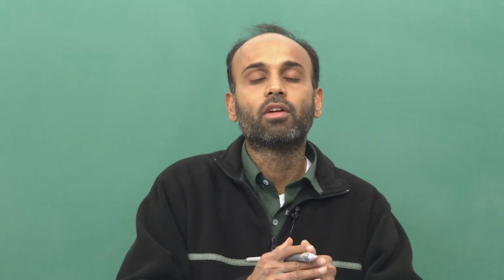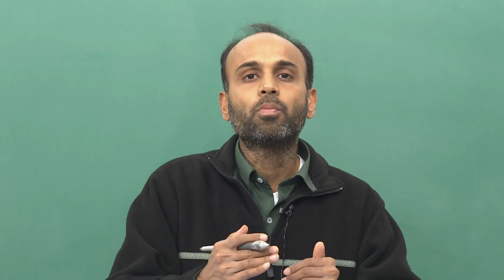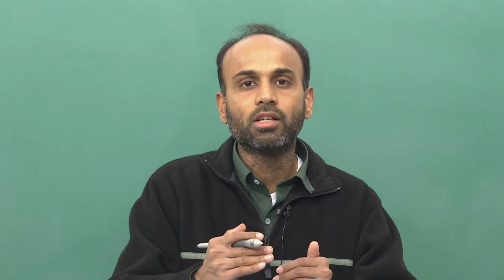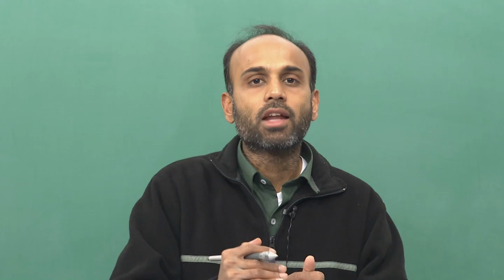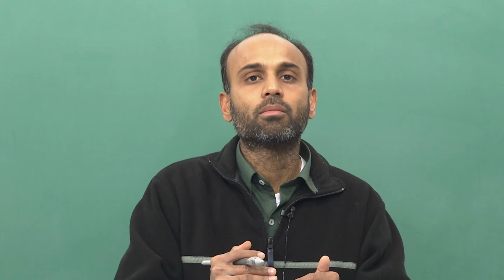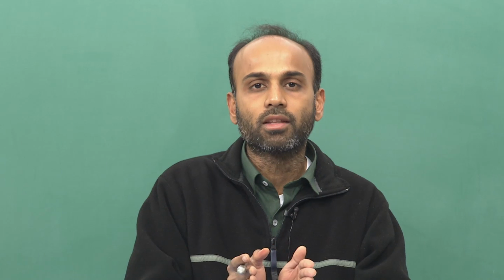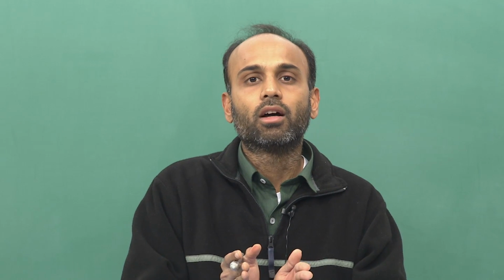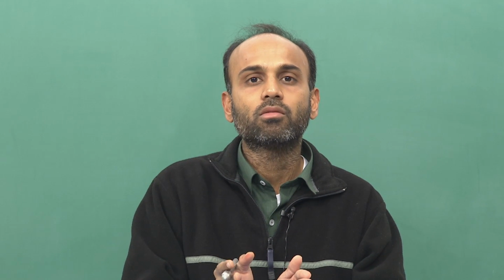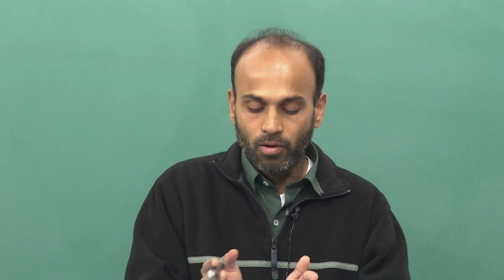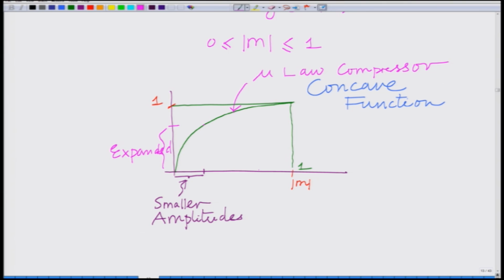Therefore, when you quantize the output of this mu law compressor, this region will contain a larger number of quantization intervals. Which implies that this region, corresponding to the smaller amplitudes, will be quantized much more finely. On the other hand, look at this entire region corresponding to the larger